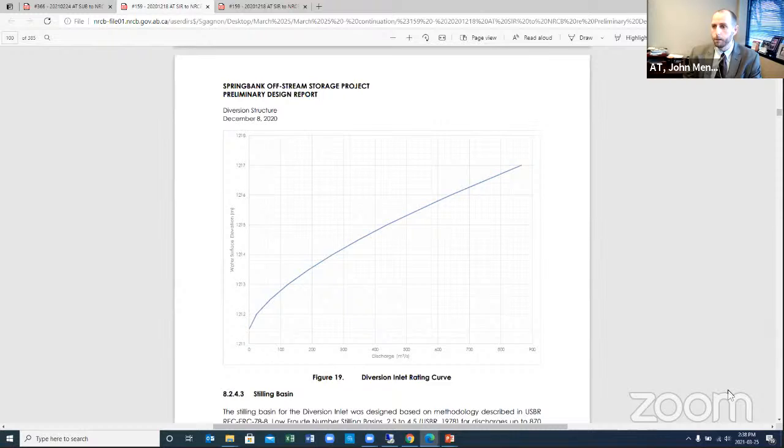And so you would have 600 going through the diversion inlet and 1200 going through the service spillway. So on this curve, during an operating condition, when we intend to divert flow into the channel, you would be at 1215.8 and putting 600 into the channel. The 1200 would go into the service spillway.